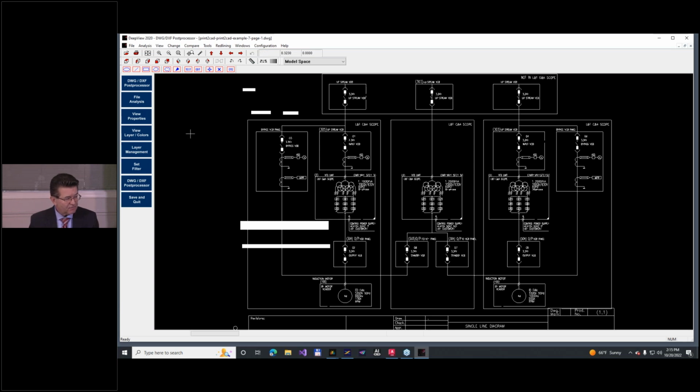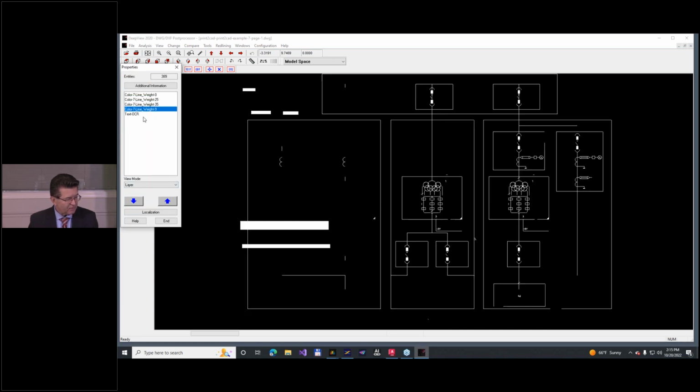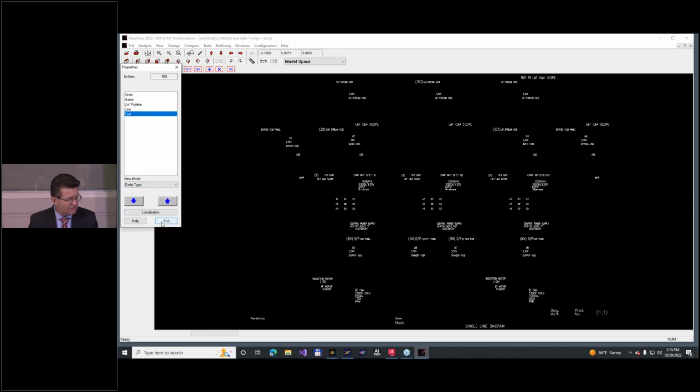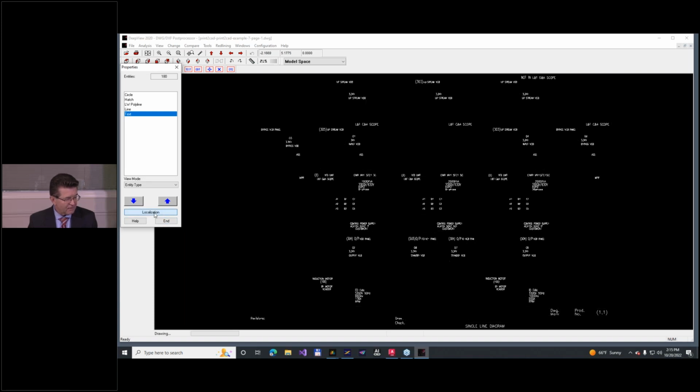And this viewer has a fantastic method here. You can see very fast the properties. Look, here are the layers we recognized, okay? Here, if you go on entity type, you can see that everything we recognized is native text. You can go here on localization and switch everything else on. Then you can go here on window.